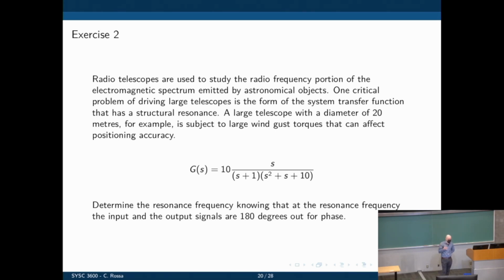There is another example of a cable bridge that collapsed because of wind gusts. The problem was that the wind was making the bridge vibrate at a specific frequency. It wasn't even a strong wind. It just so happened that it created a frequency of vibration that matched the resonance frequency of the bridge, and the bridge collapsed.